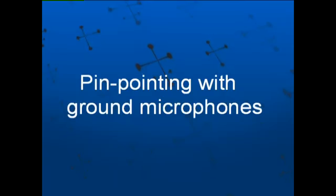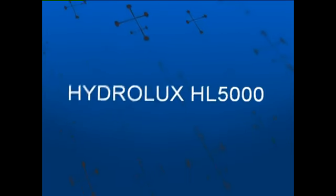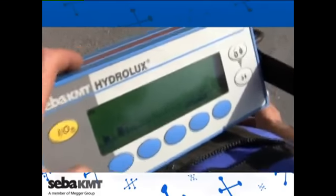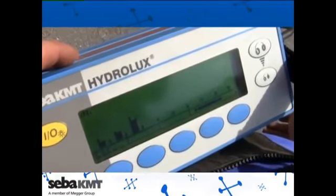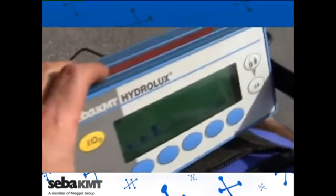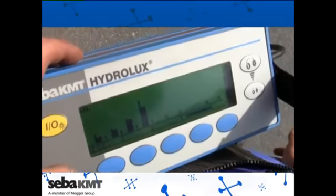Pinpoint location using ground microphones. Hydrolux HL5000. After using the Correlux P250 correlator, the surveyed leak point was then confirmed and pinpointed using the Correlux HL5000 acoustic listening system. The histogram function of the HL5000 helps the user to locate the position with the maximum noise level quickly and easily.